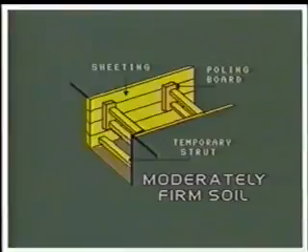The other difference between timbering in firm and moderately firm soils is that the vertical boards are placed close together in case of moderate soils. In loose soil, the timbering can be done in same way as that of moderate soils.